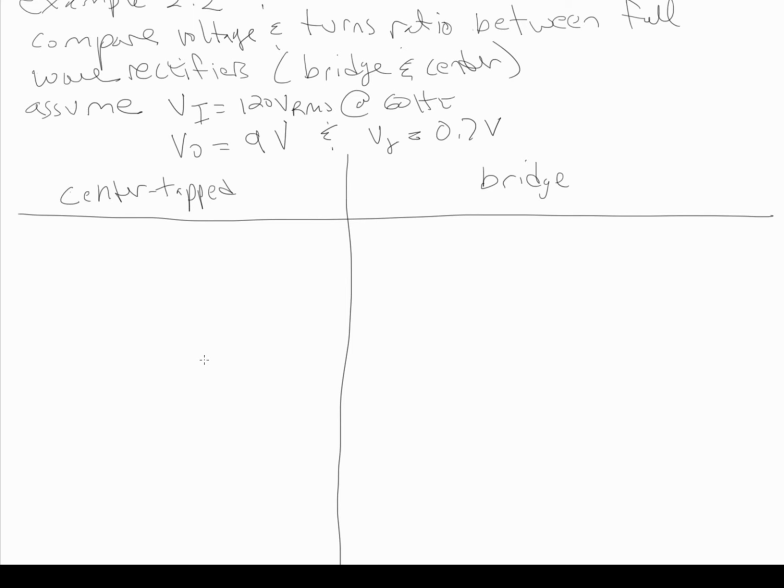So I don't know if they tell you, but I guess this is 9 volts peak. So we say your V max, that your V out is going to equal 9 plus V gamma, which is 9 plus 0.7, which is equal to 9.7 volts.